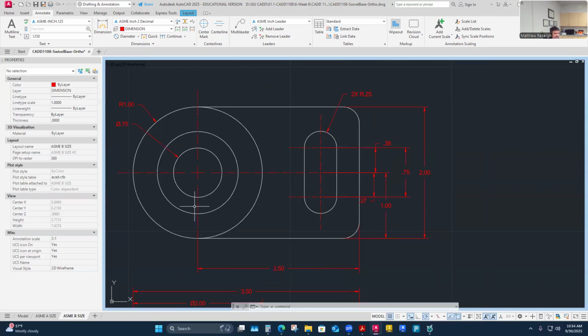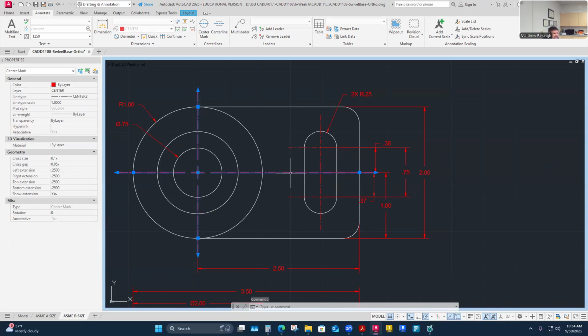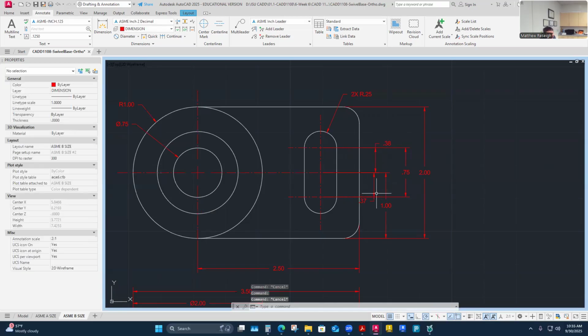I think from this center line over to this center line here is going to be my other control. That's what the 2.5 is. That's the way I read this. This is going to be my control hold. It's out 2.5 inches to this. So likewise, I chose to do the Y control off of this center line and show the differences. That's critical. Now I'm doing the X direction control.